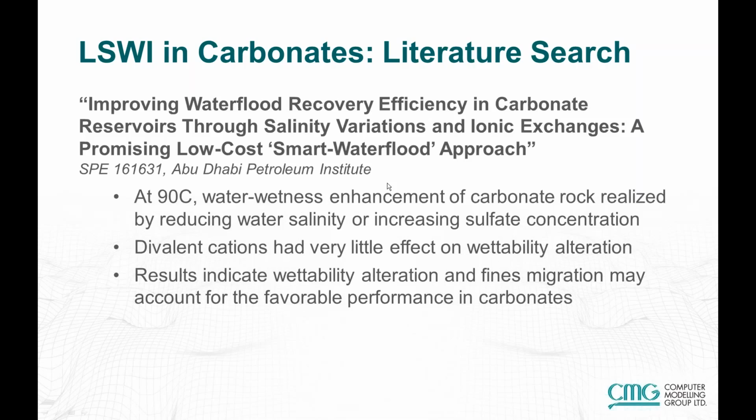Now this paper from Abu Dhabi Petroleum Institute concluded that at 90 degrees C, the water wetness enhancement of carbonate rock is realized by reducing water salinity or increasing sulfate concentration, whereas the divalent cations had very little effect on wettability alteration. So their results indicated that the wettability alteration and fines migration may account for the favorable performance in carbonates.